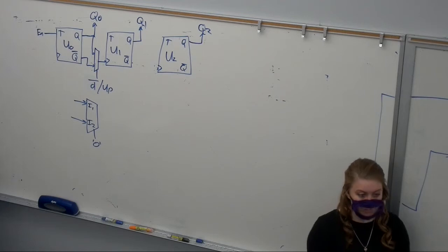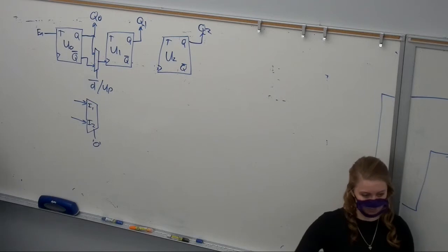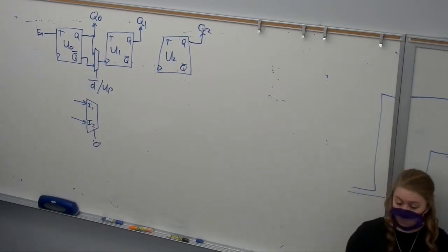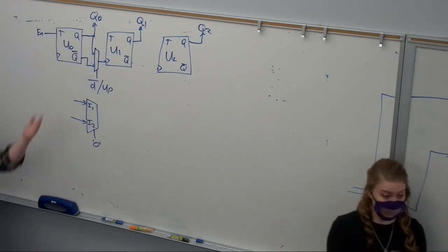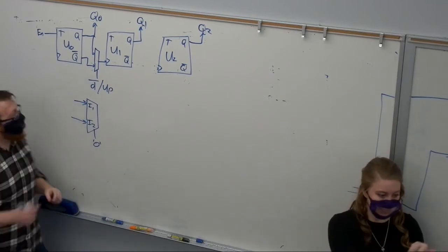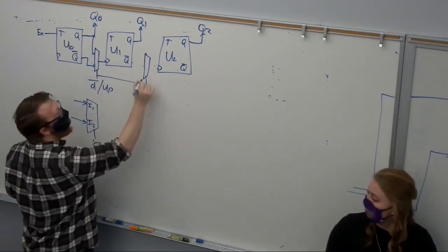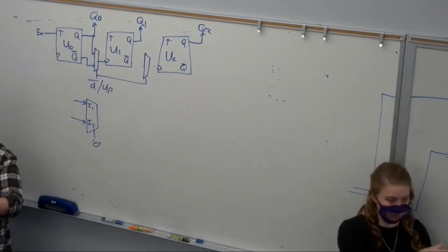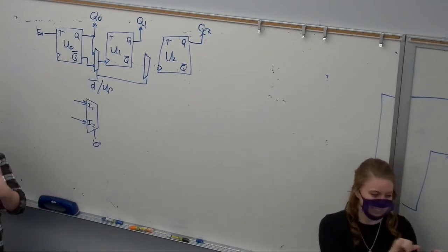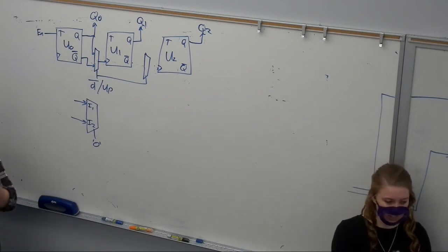Ah, we did. We built an up or down counter using T flip-flops. And so you just add a mux in between U1 and U2. Yeah, exactly. We just repeat this circuit over and over again. And you would tie both of them to the same up-down signal, right? Because it wouldn't make sense to have half counting up and half counting down, unless you wanted a sequence generator. That would generate a reliable sequence, but it wouldn't be a counter.